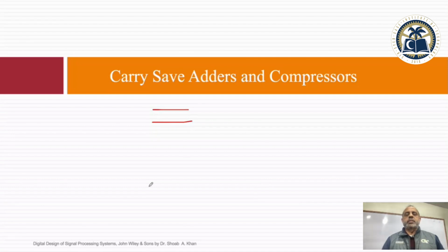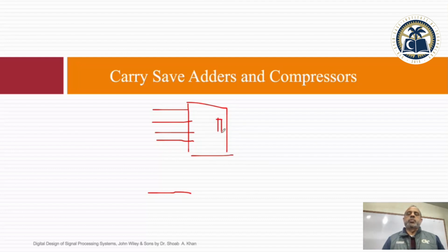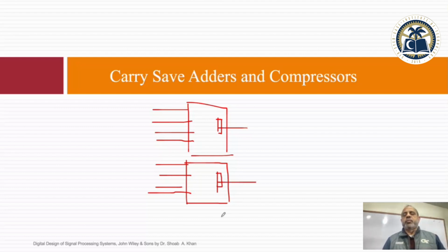So this may be a better way, that you have these 16 numbers getting in, and you make clusters of 4. So these are the 4, and you have a module where you are registering all these 4 and also registering the output. So the register that you are using to store the maximum of the 4 inputs will act as a pipeline register. Again you have 4, and you do exactly the same module which registers all these 4, finds the maximum and stores it in another register, which is the maximum register. So this register will act as a pipeline register. Then you have another 4, another 4.